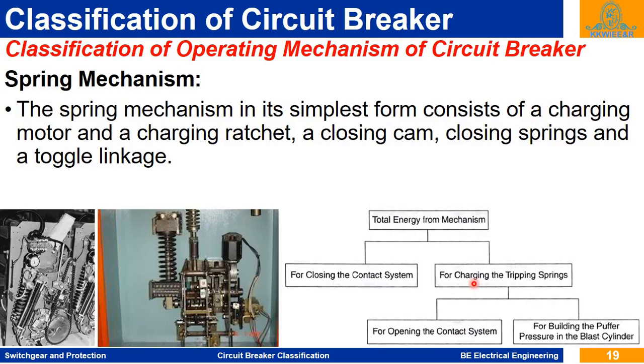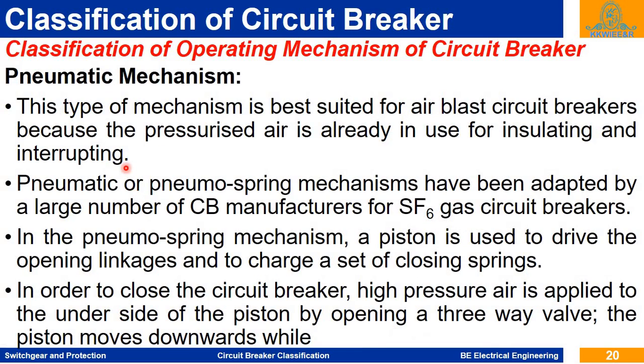Then, for charging the tripping mechanism, for opening the contact system, and for building the buffer pressure in the blast cylinder, this total energy is stored in the springs. One is for closing the contact and another is for opening the contact. So next is the pneumatic mechanism.